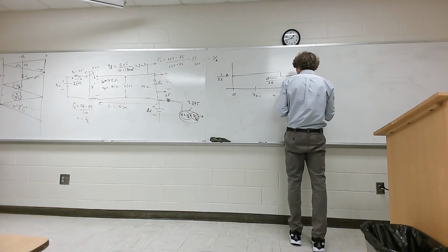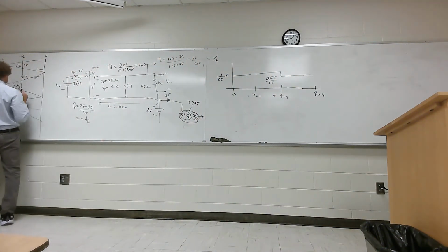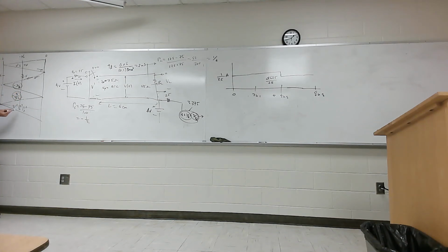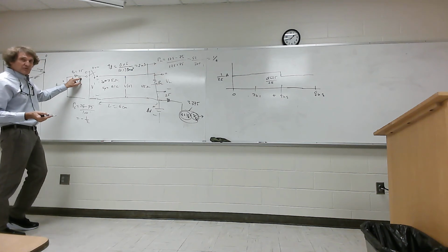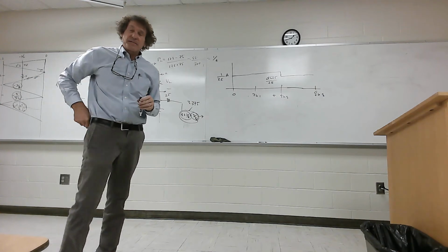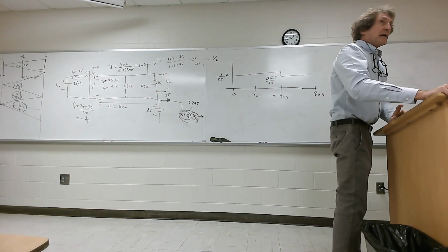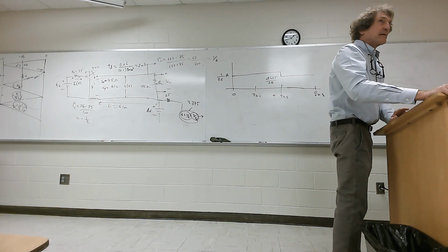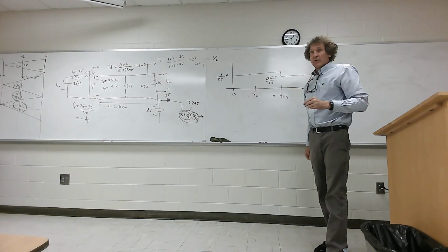So that would be at 4, 6, 8 nanoseconds, right? 8 nanoseconds. Now what happens? Now you have to take that value, and add the next reflected term, which we didn't even calculate, to it, and find the voltage then across here, and subtract that from 4 volts to see how much voltage is across that resistance. But that's how you would get the current that would be going onto the line, the additional current. And it's going to steadily go down. It should be less.